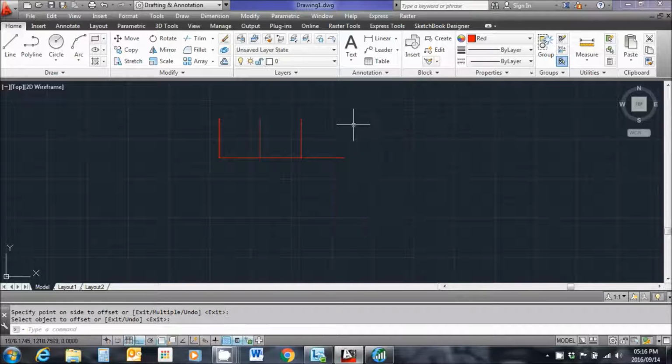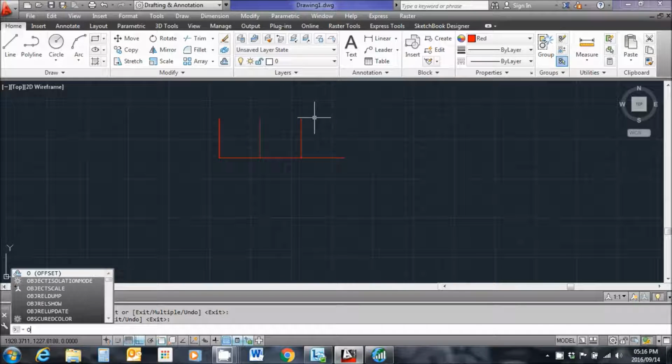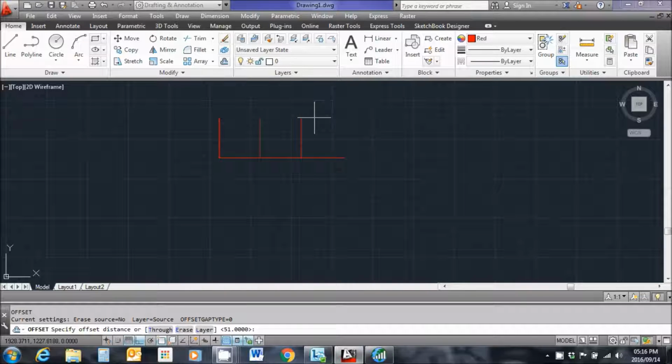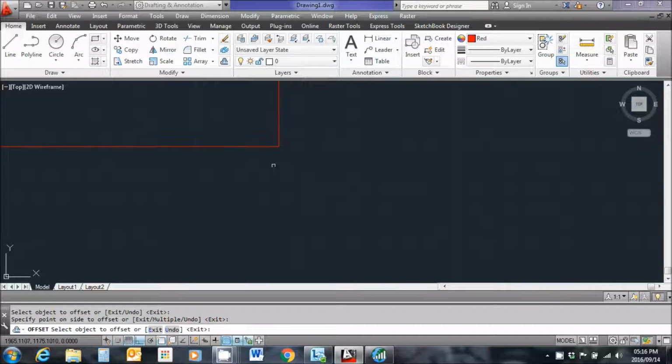And now manhole A6 is the last manhole, and that is 53 meters away from manhole B3. So offset 53 from this point to that point, and you'll see that that lines up with the end of my line.